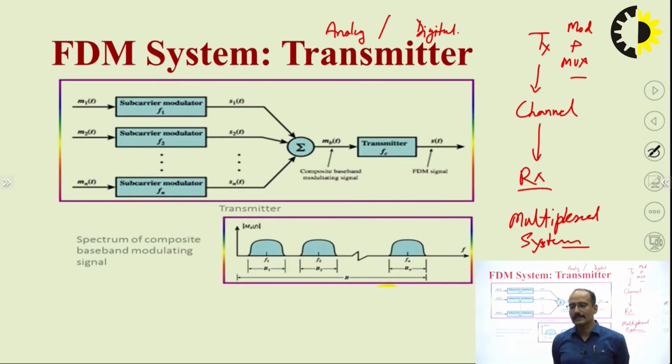In a time division multiplexing system, if there are 3 users, then we take a frame of 1 second. In that 1 second frame we use the complete 300 megahertz frequency band for a single user for 1/3 second. That means we divide the 1 second slot among the 3 users with 1/3 second each. For 1/3 second the complete bandwidth is available to user 1, so that it can send data at the maximum speed. So, in digital transmission we use TDM.